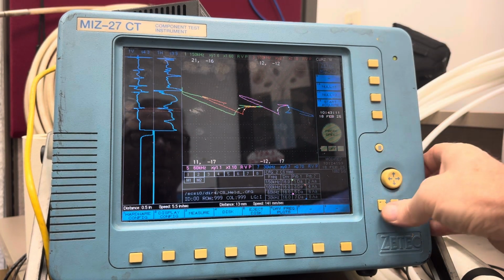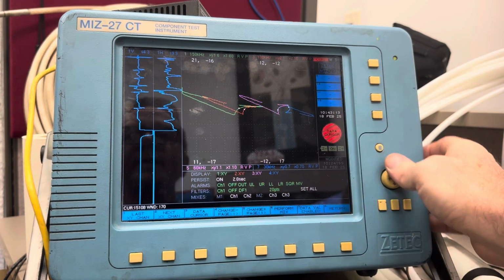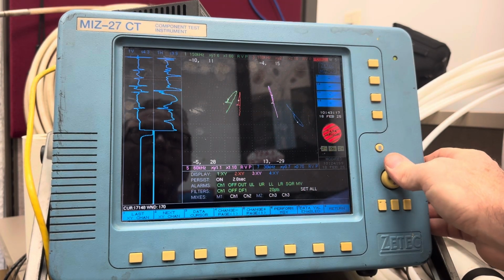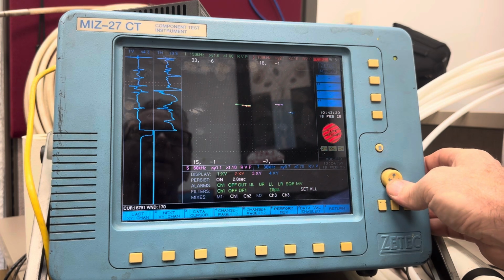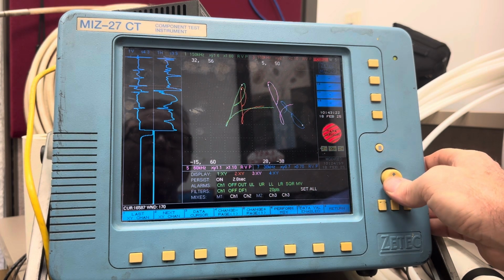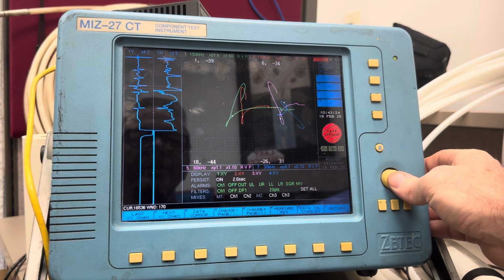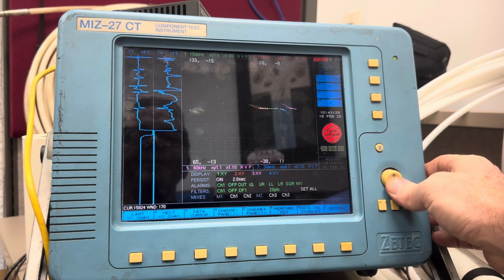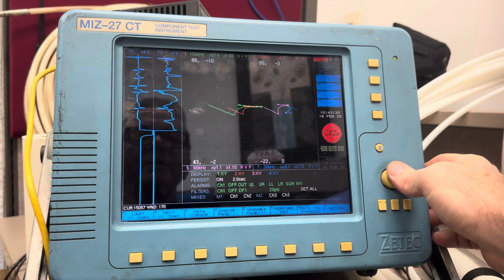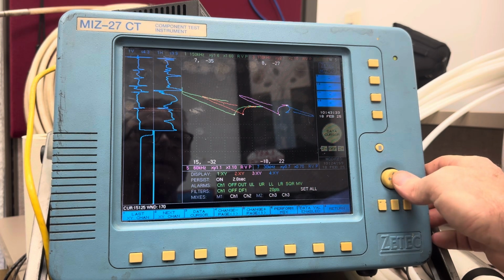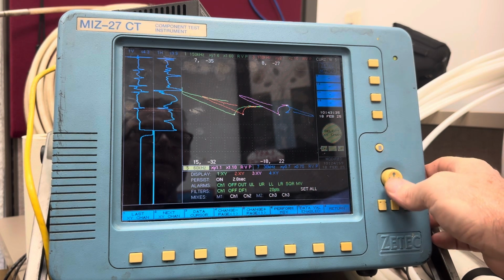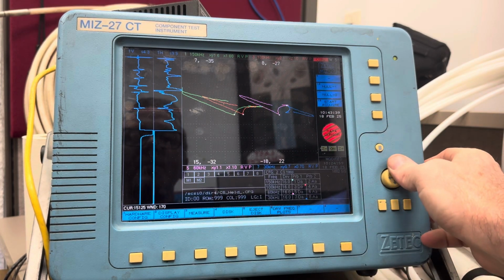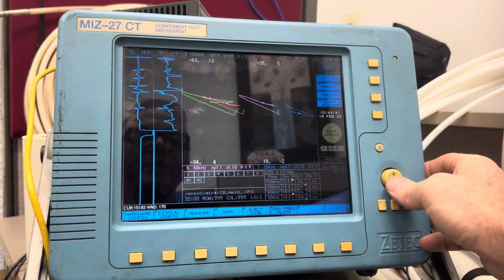Normally, you would want a 100% signal to look more symmetrical, like these, but rotated over at about 40 degrees, maybe 35 degrees if you set probe motion horizontal. But just know up front that that is not the kind of signal that you want during an inspection.